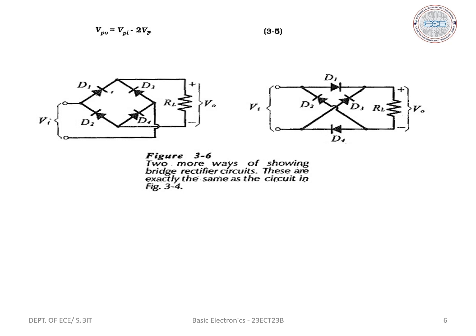In this circuit, the secondary winding resistance is formed by two series resistances. Hence, the capacitor charges very rapidly as soon as D1 or D2 or D3 or D4 starts to conduct. The load resistance RL is very much larger than the resistance of the secondary circuit.